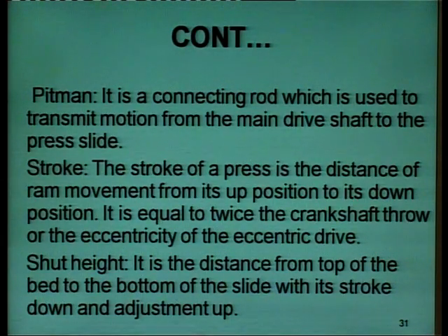Now, the stroke of the press is the distance of ram movement from its up position to its down position. Next comes the shut height. Now, it is the distance from the top of the bed to the bottom of the slide with its stroke down and adjustment up.